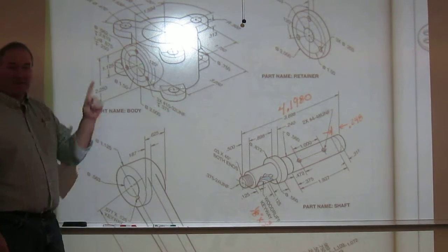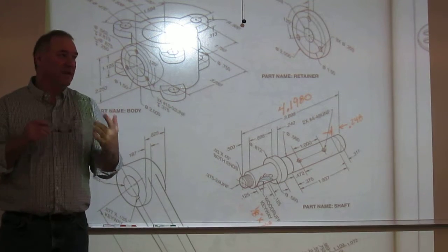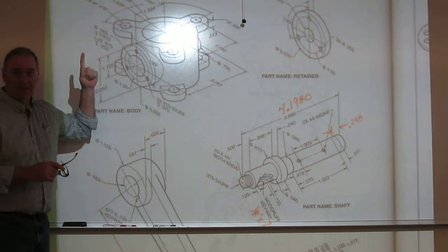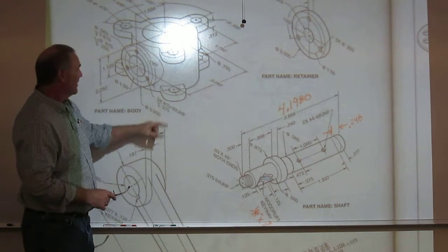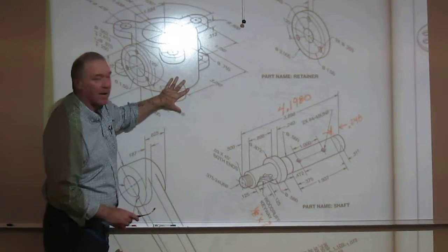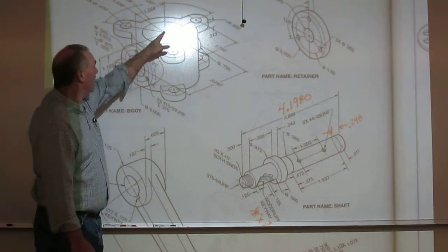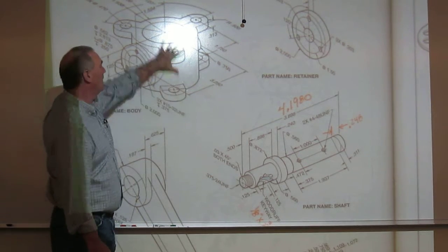Okay. Now, the second thing I had on my drawing outline was what? Datums. Get those datums. There are two datums on this thing. You have one datum, which is a vertical axis right here, and it controls the location of everything to do with this body right here. So if I have one line right here, I will use that datum to build all these other shapes.